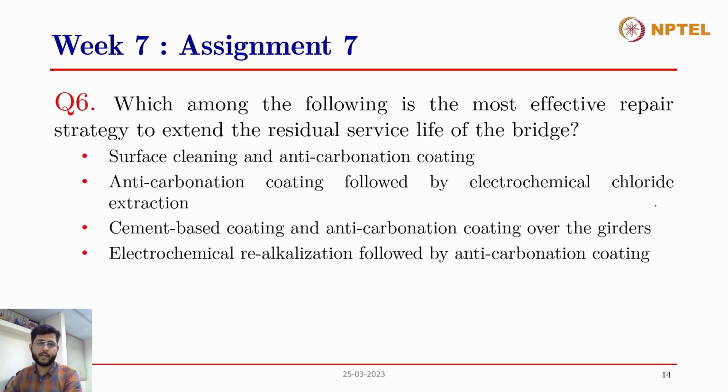Therefore, we have to choose the effective repair strategy. And what should be done? The first option is surface cleaning and anti-carbonation coating. Only cleaning the surface won't help because the carbonation front has already surpassed the cover depth, and it is at the rebar location now. So just anti-carbonation coating won't help because the pH around the steel rebar is already sufficiently low because the carbonation has already occurred.